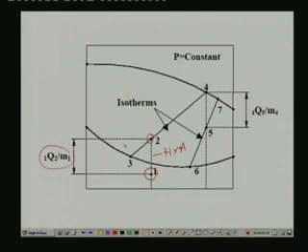So, I can easily find out this enthalpy, and during this process your concentration remains the same. So, zeta 1 is equal to zeta 2 during this process, but point 2 lies in the two phase region. This is the liquid plus vapor region. So, that means at this point you have saturated liquid at point 3 and saturated vapor at point 4.